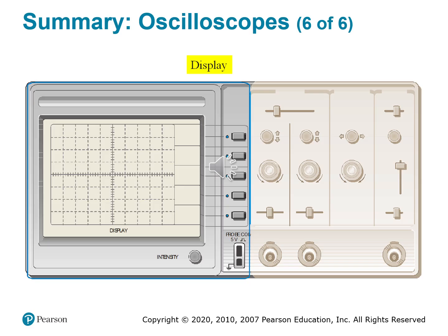The grid itself, we call it a graticule. It's an older term, but it's what it's called. The screen is covered with a grid made of vertical and horizontal lines. You have vertical divisions that show amplitude, like voltage, as set by the volts per division knob. You have horizontal divisions that show time, as set by the seconds per division knob. So each small box is a measurement unit, turning the screen into a graphing calculator for waveforms.